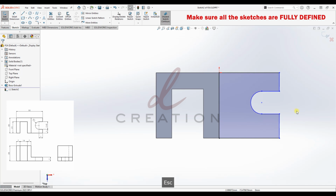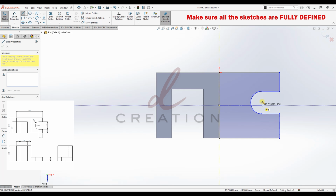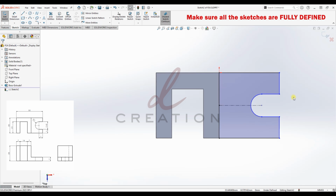Now we have the complete sketch in a closed loop, and then I'm going to give the dimensions for this. Before that, I'm going to add a center line from the midpoint of this line to the center of the semicircle, and then I'm going to make sure the center line is horizontal. This is so we can make sure that this line and this line are at the same width.